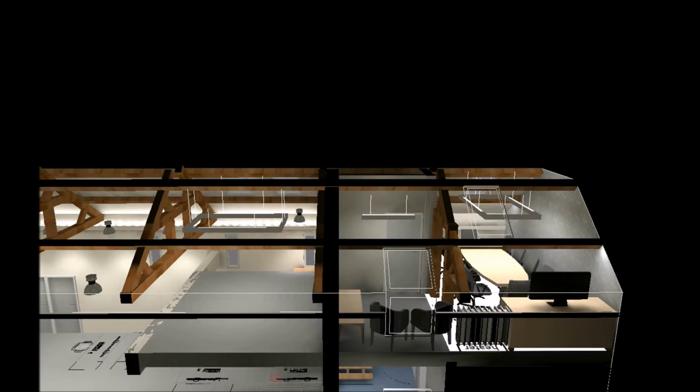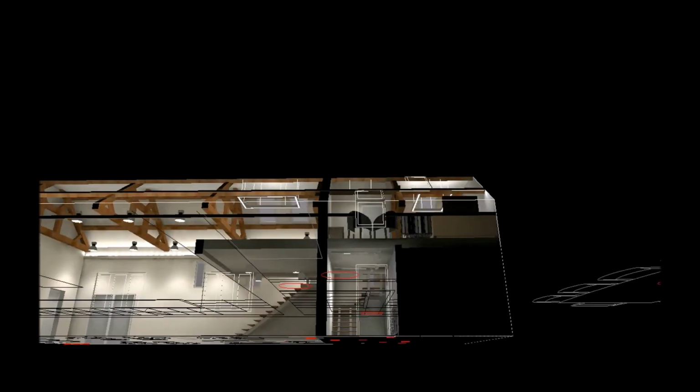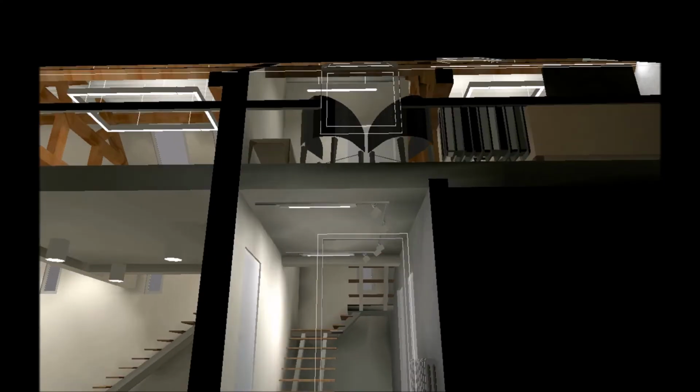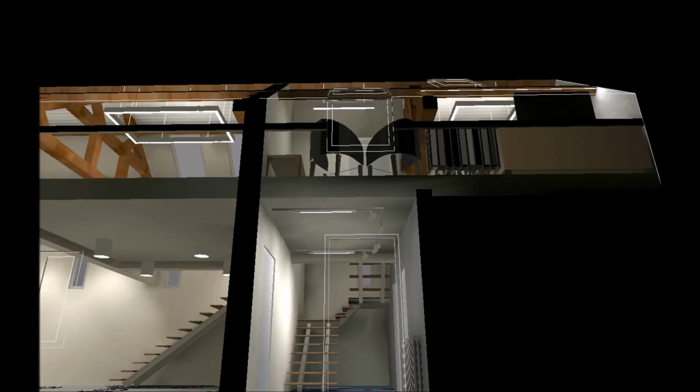And then the only other element to talk about is the entrance area, where I've gone for a U-shaped track to get past the smoke detector we have in the middle there. A couple of these linear discrete luminaires that clip into the track, and then we've got spotlights which are focused on the wall or wherever you may put photos or displays or whatever. So those are very much a factor to be decided. For the purposes of this scheme, I've put 5 10-watt spots.